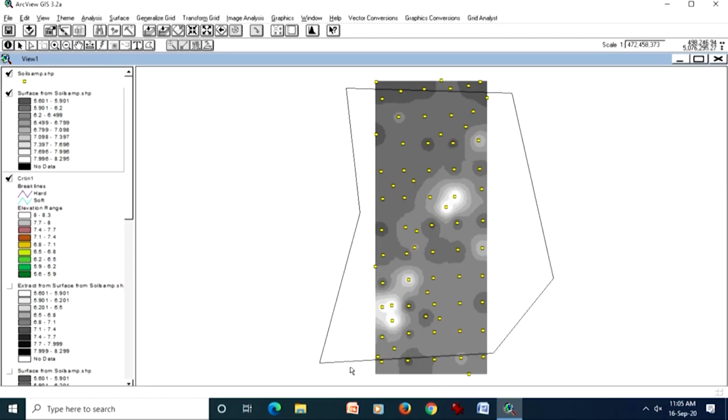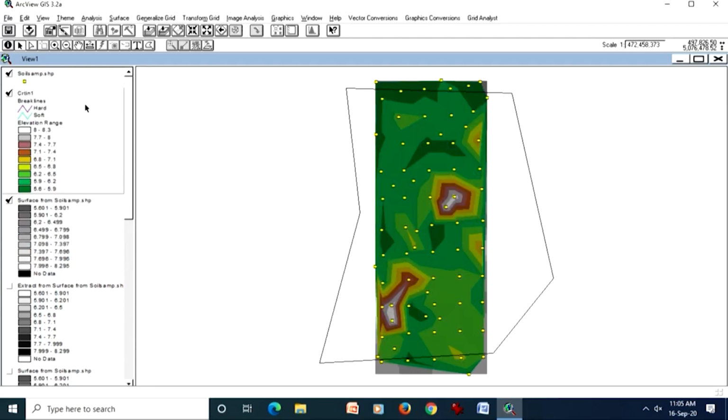If you compare this with the TIN, the TIN will also go, but theoretically or practically the raster has to be stored in rectangular or grid form, because it is a two-dimensional matrix, and the number of rows and columns need not be the same. So only two shapes are possible, rectangular or square. But in case of TIN, this condition is not there.